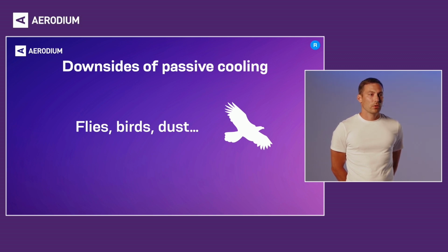Also, the dust and smaller particles that can ingress the wind tunnel actually pose a danger to your customers. So once you take the proper measures to not allow these particles to come in, this is definitely going to be another point of resistance for the airflow, which in turn will increase the power consumption of your wind tunnel.